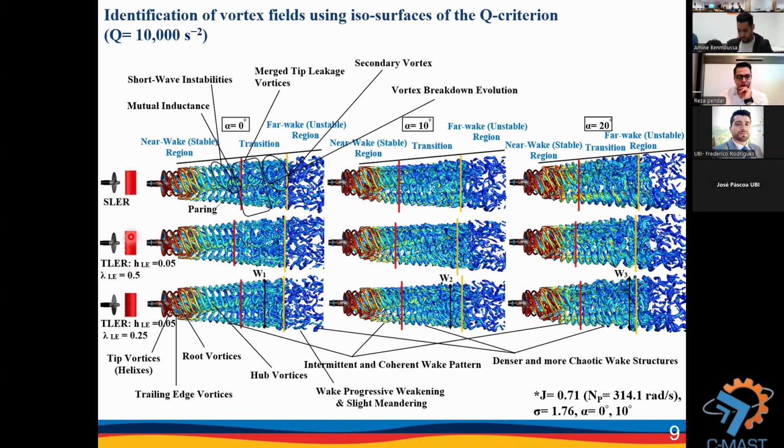This tubercle rudder diminishes the noise level by manipulating the wake structure behind the surface of the rudder, specifically at higher rotational speed, for example, at a higher deflection angle of the rudder in maneuvering condition.